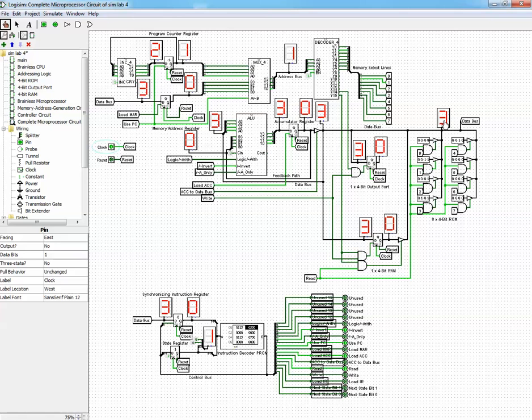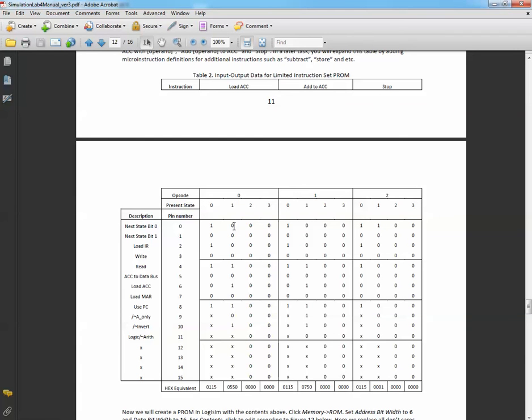We have ticked the first clock cycle, and we will now tick the second clock cycle. What do I expect to see? I expect to see this is a 3, and it is passed through to the input of the accumulator register, and once I tick it, the 3 becomes here. Right now we are in the second clock cycle, which has been ticked, so we have gone to state 00.